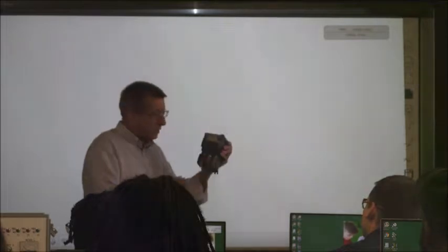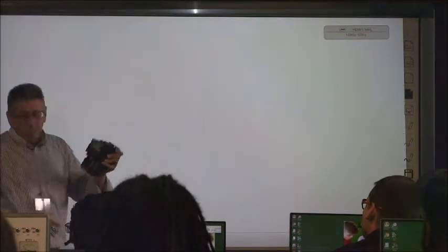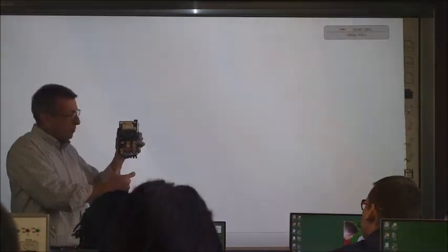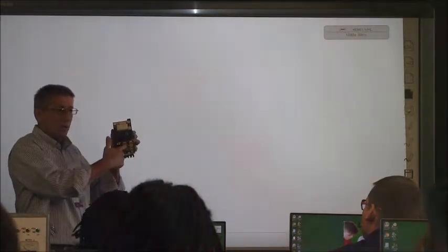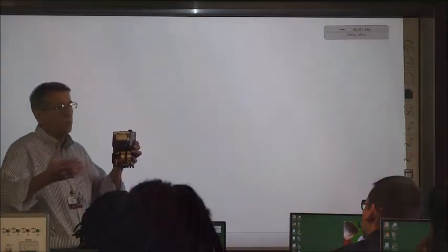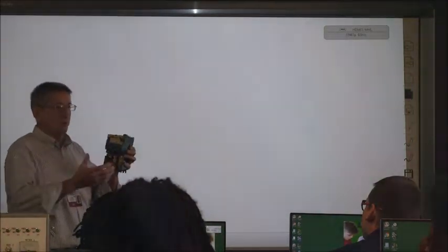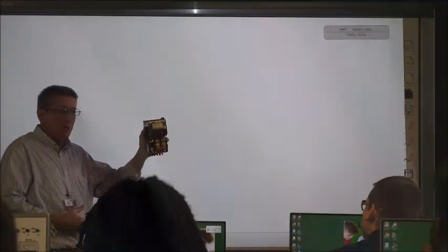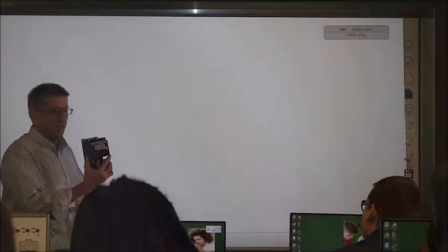Put Linus in. So yeah, motor starter. The old time motor starter with the heaters. There's probably still some of them out there. Actually, back years ago, when I went through all that stuff, the classes that I was in, we would have to size the heaters according to the motor size. We looked at the specs of the motor, then went to the tables of the documentation, sized the heaters, sized the motor starter. We went through every little detail on sizing everything to run a motor. But I know they don't probably get into that these days.